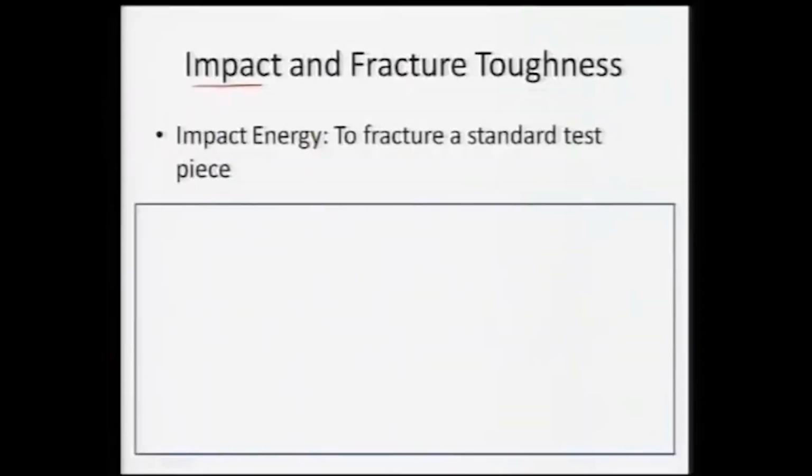So, that is the overall deal with the micro and nanocrystalline materials, and eventually what happens is that the impact and fracture also is dictated by the grain size of the material. Like I said earlier, the tortuosity has increased, so also the strength of the material has increased. At the same time, the nanocrystalline grains can also realign themselves. So, now they can absorb much more shock, and then they can impart very high impact energies, or they can have very high fracture toughness.